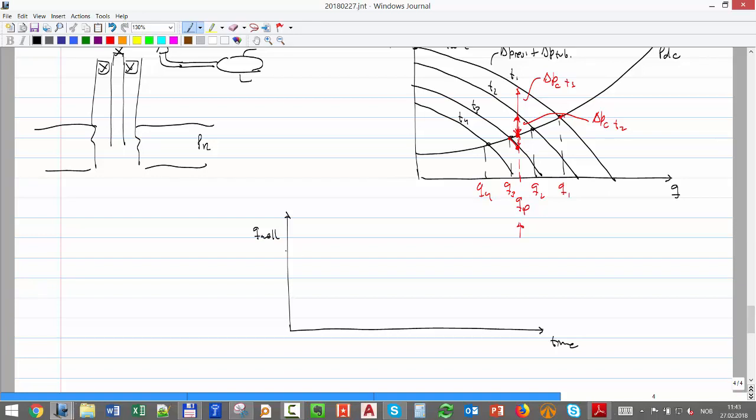For time one, you will have Q plateau. Time two, you will also have Q plateau. But what will happen in time three if you don't install anything? Decline. So here you will have Q3, and here you will have Q4. And there you managed to find your production profile for how long you will be able to produce that Q plateau, by taking into account the effect of the reservoir and the production system, and assuming that you're controlling with the choke.